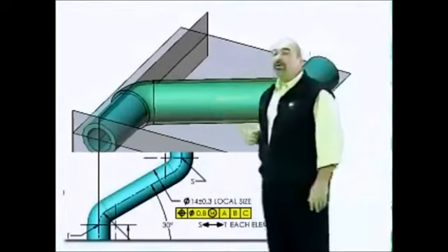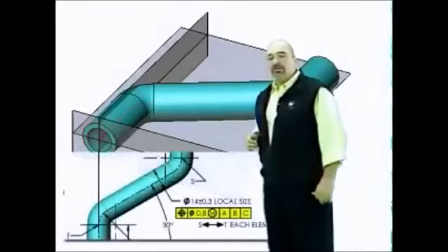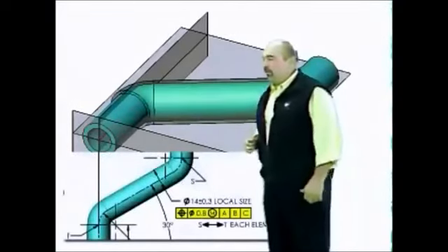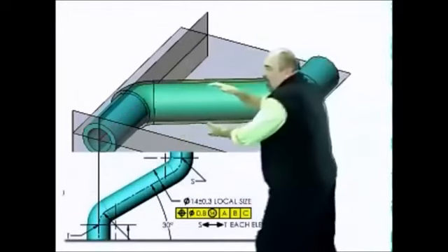Each element or slice must be within 0.8 millimeters of its basic location if it's made at its largest size or maximum material condition. Together, these slices define a boundary that the surface of the tube may not go outside of.